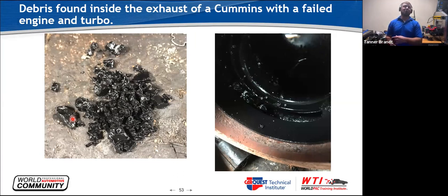So you need to make sure all the debris from whatever failure is gone. You need to make sure there's nothing in the intake. You need to make sure there's nothing in the exhaust. A lot of the repeat failures of turbos I saw when I was rebuilding were like this: maybe an exhaust valve came out and ruined the first turbo. They put a new turbo on it, never cleaned the exhaust, and pieces of the valve were still up in there, and then the valve would come in and ruin the new turbo. Then they'd send the turbo in saying something was wrong, and I would take the turbo apart and find more pieces of valve in it. So always do yourself a favor and make sure that you don't have any debris.